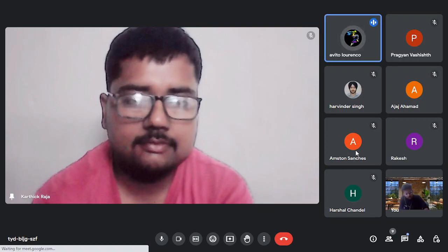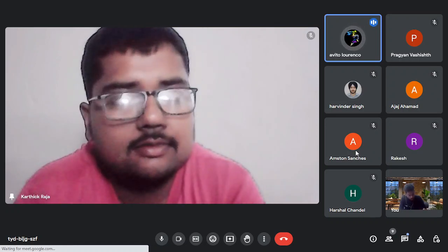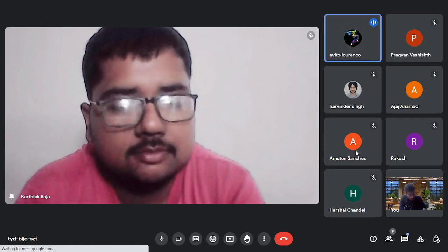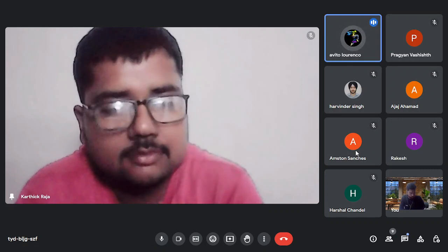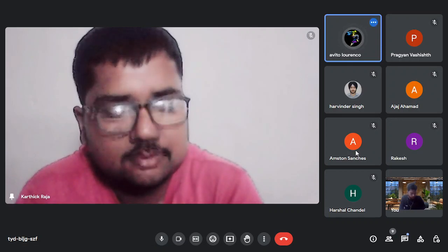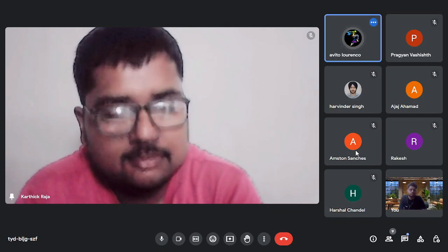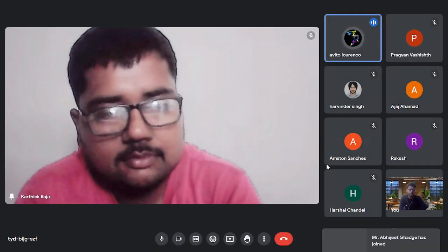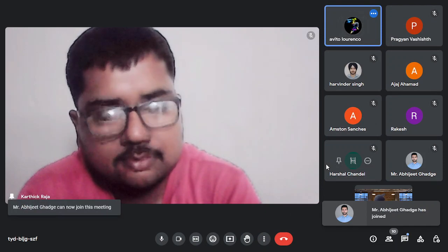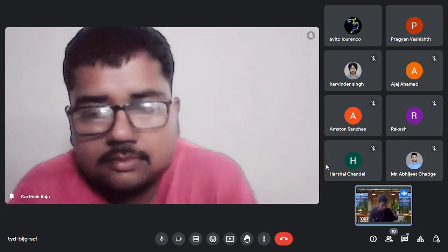The first cross question was, in the ships, if ultrasonic testing is so good that we don't have to spend any material and can just reuse it again and again, and in dye penetration testing I'm wasting all of my sprays because I have to spend on the dye as well as the developer, and this spray is highly toxic, then why do the ships still use dye penetration testing compared to ultrasonic? Why still use dye if ultrasonic testing is so good?